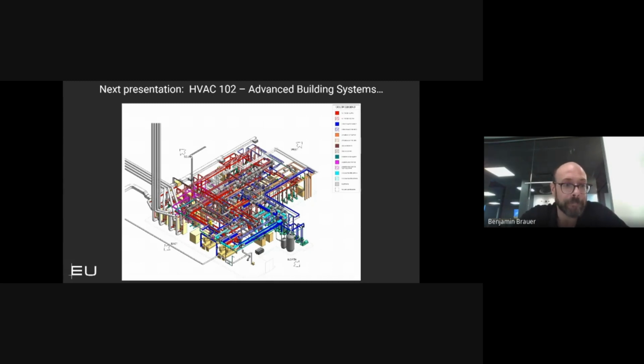It was actually one of my first BIM projects, a full 300, well, 300 plus anyway. No prefab elements, or not much in the way of prefab elements yet, so we didn't take it to LOD 400. For those that don't know what I'm talking about, BIM and LODs and whatnot, there's plenty to give you a lunch and learn from our virtual construction side, but essentially that's the level of detail that the 3D models get up to for purposes of design coordination or prefabrication that some of the mechanical trades or architectural elements can be utilized for.